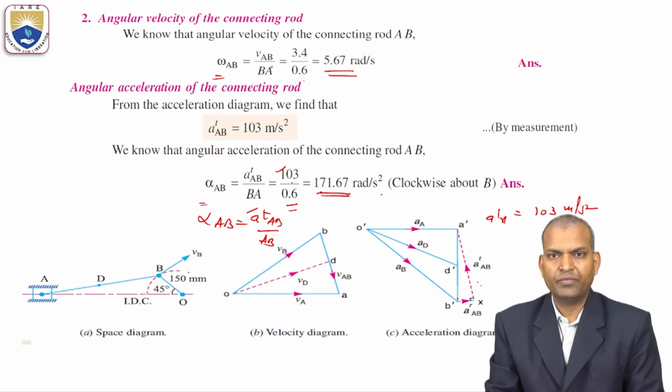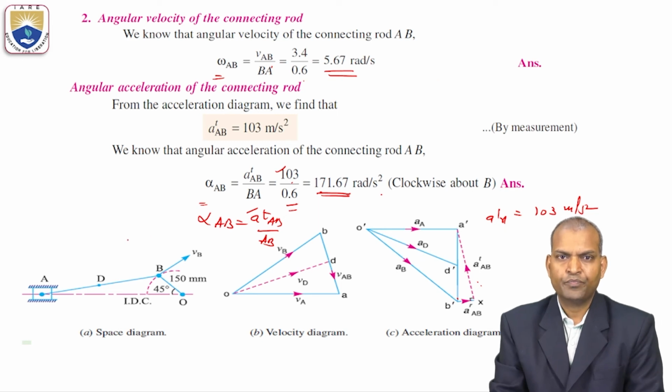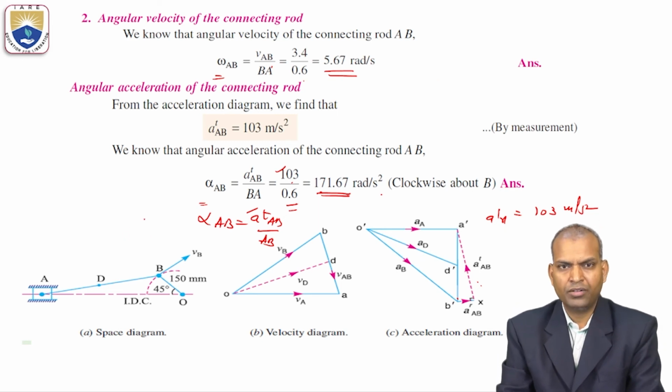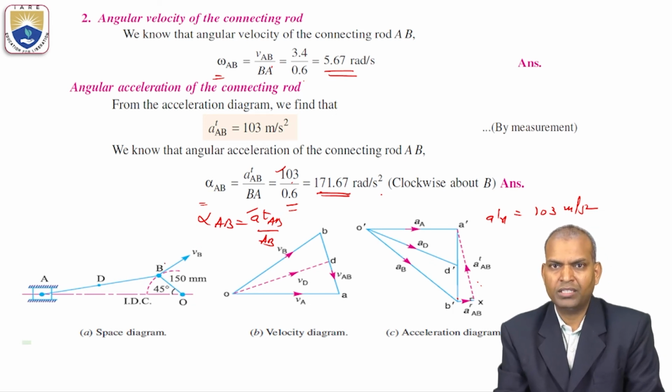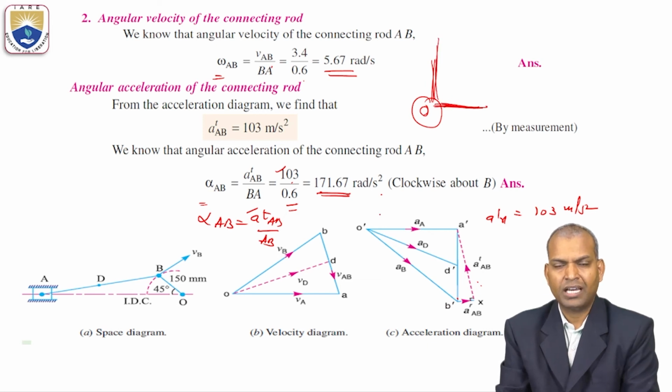You cannot draw the space diagram at one corner and the velocity diagram at another corner. If you have enough instruments, especially we need 2 set squares or 1 mini drafter. If you have a mini drafter, you set the scale. Mini drafter has a large scale and a small scale, no? You set it parallel to one of the configuration diagram links, and automatically the large scale indicates the normal line. That normal line you can draw.